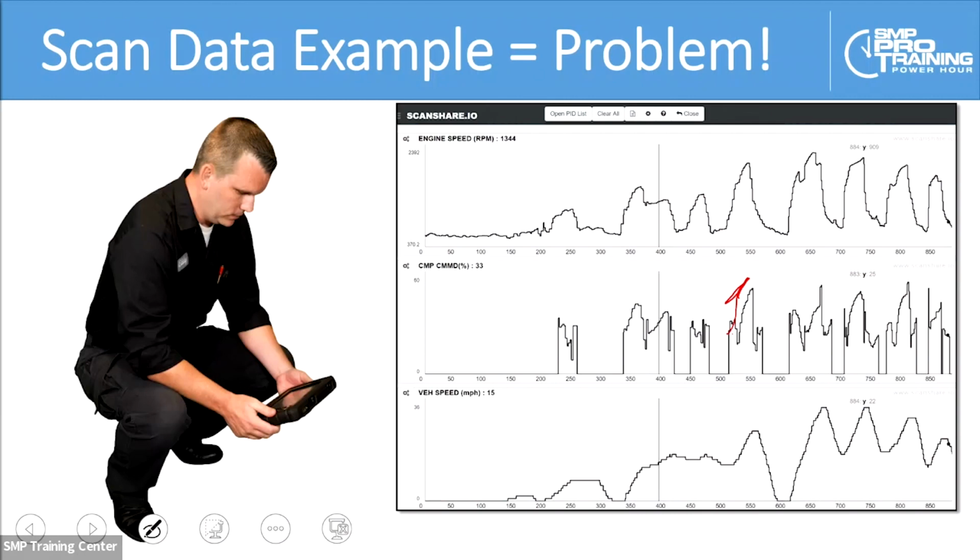That's the command to the oil control solenoid. That's an unhappy PCM. He says, hey, you're not where I want you to be. So what does he do? He continues to increase the command to the solenoid. And you can just hear that PCM saying, come on, I know you can do it. I know you can get there. And does it ever get to the position that the PCM wants it to be? I don't know. But that said, we've got a problem here.